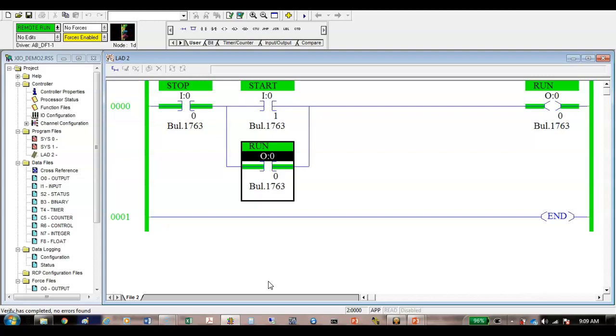Oh, I know what it is. So here I'm going to open the switch, and what did it do? It dropped out, right? But this looks wrong because in my relay logic diagram, it's drawn as a normally closed switch. So what people want to do is use that normally closed contact. But what you've got to understand is we want this thing to be true when it's what?